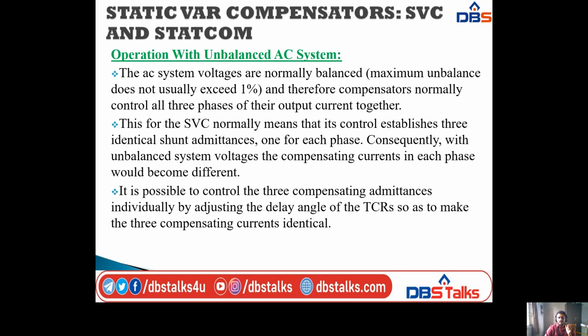It is possible to control the three compensating admittances individually by adjusting the delay angle of the TCR, that is thyristor controlled reactors, so as to make the three compensating currents identical.